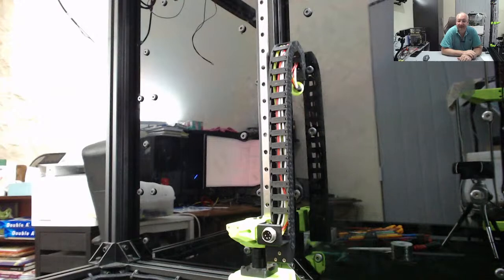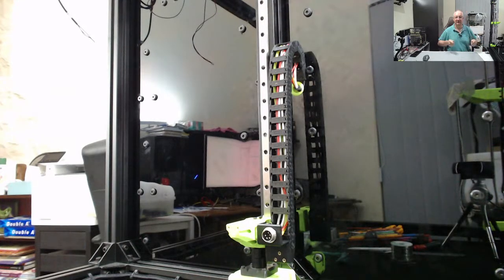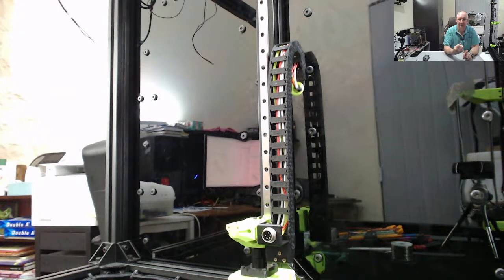I've got this crazy idea that, instead of running a 500mm bed permanently, which draws 1500 watts for whatever print, I also purchased a 300mm bed. And so I want the ability to pick up my bed, remove it, and put the small one in. And to do that, the big thing is I need to get the bed heater to switch over, the bed thermistor to switch over, and the earth cable that I'm going to be running to the bed.